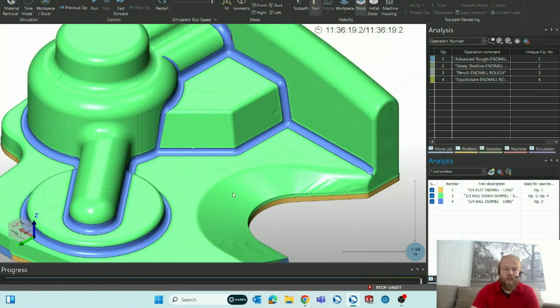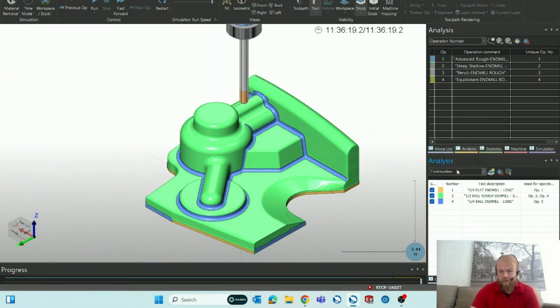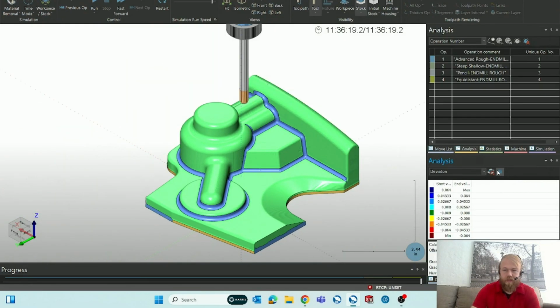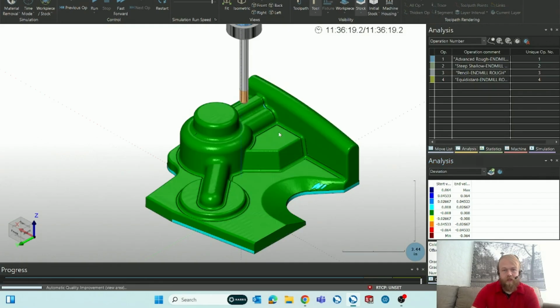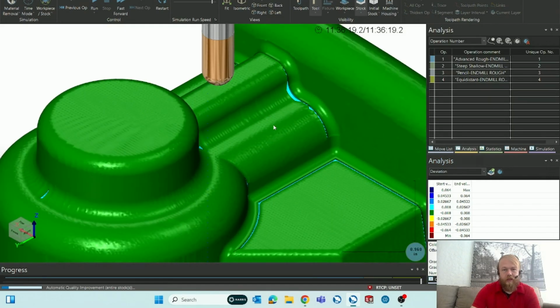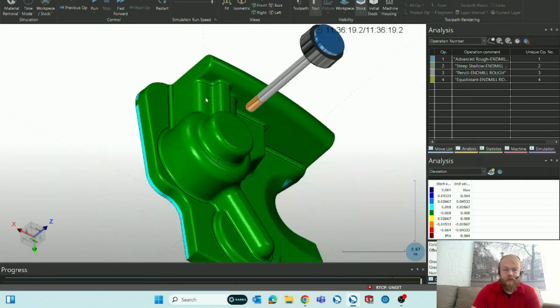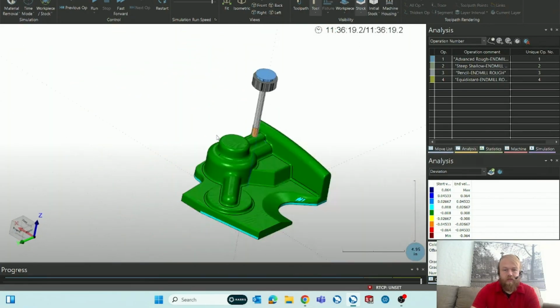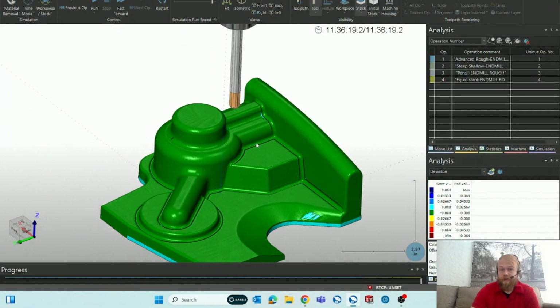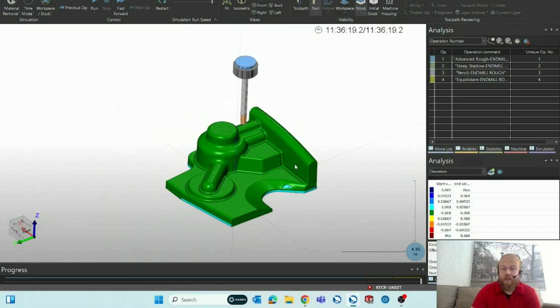Tool number 2 got into the green. Blue was tool number 4. That's under this analysis page with the deviation report here as well. So that cleaned up with the gouge check here, and that's the main reason for the gouge check and tilting the tool.